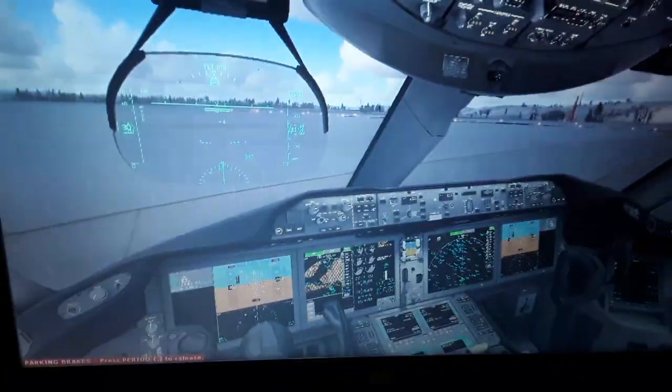We use the inertial reference alignment. For that, using the flight management computer and the IRS panel in the overhead panel, we need to align the aircraft. We have also the magnetic north pole and the geographic north pole, and the magnetic variation depending on where we are in the world. We can see also the navigation aids, the world stations, ADFs displayed in the navigation display. Also the waypoints, which are horizontal and vertical navigation fixes, and altitude and airspeed constraints. The aircraft is going to have to fly through some waypoints on this flight.